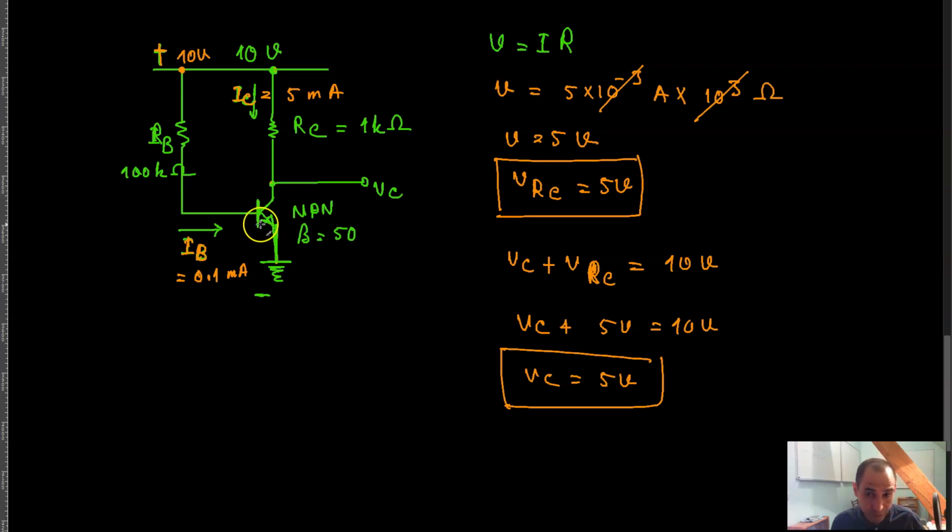And what that means, and of course we will get to that in a couple of circuits, hopefully in this video, is that since there is some voltage drop across the collector emitter junction of the transistor, you cannot say that the transistor is turned on. The transistor is not yet turned on.